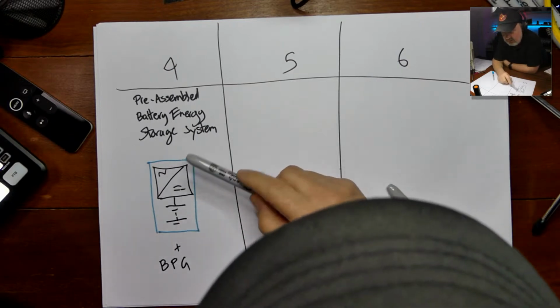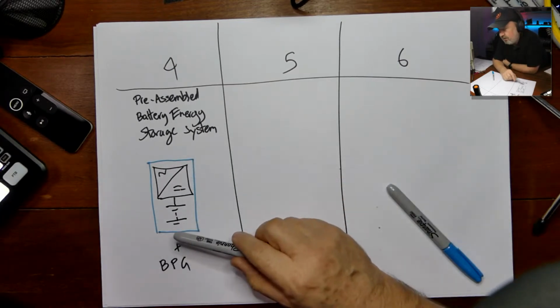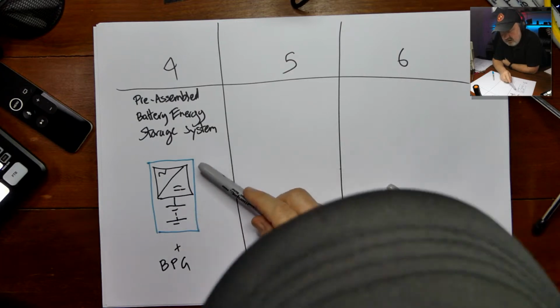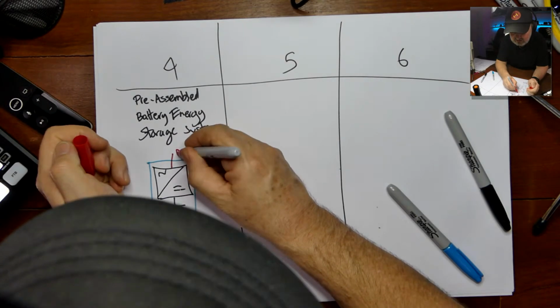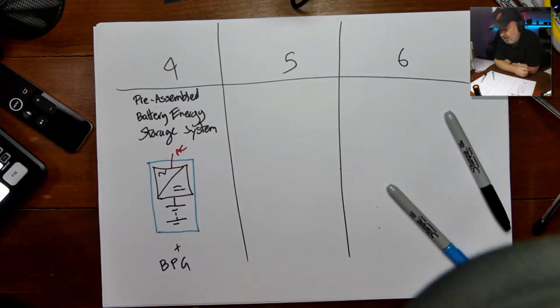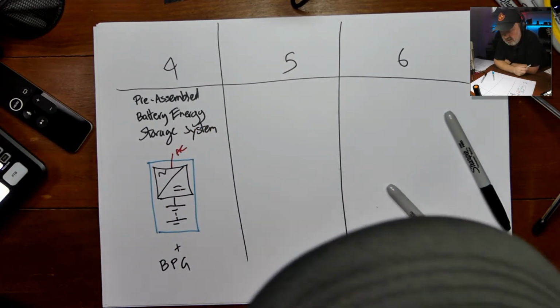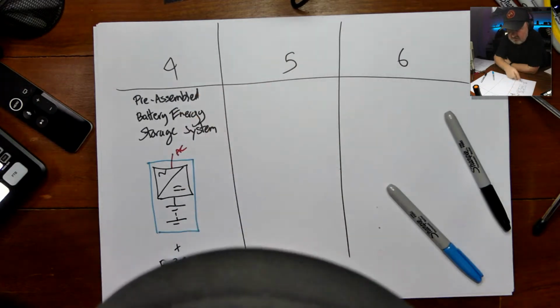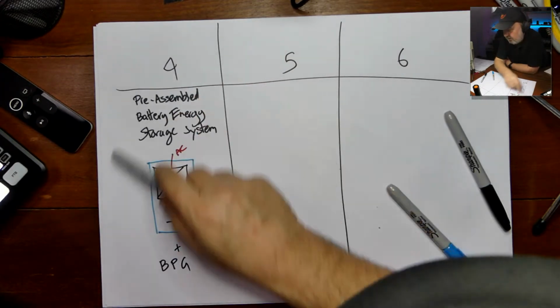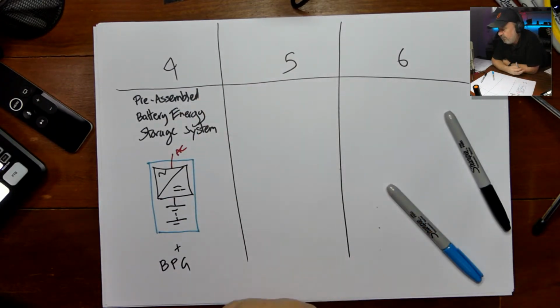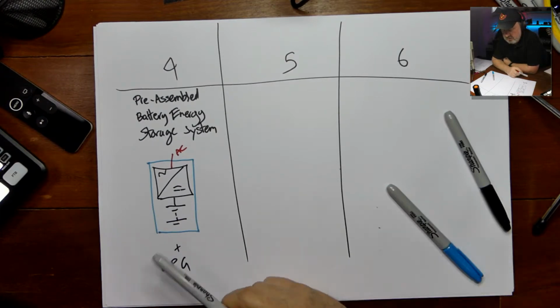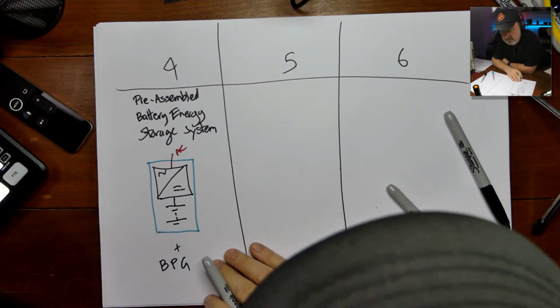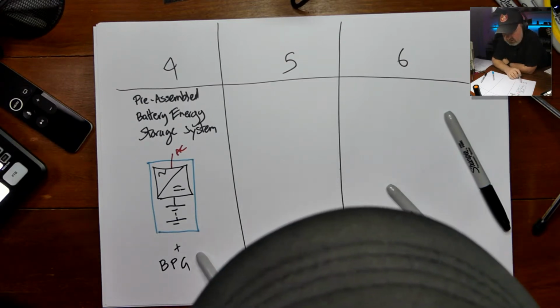So you have to be pre-assembled, with the inverter and the battery as one. Therefore it's an AC output device, so the output of this system is only AC. You don't have any DC terminals to connect to, and it's a Section 4 solution. Products like Sonnen battery, Tesla, and Varta are some examples of an all-in-one BESS, battery energy storage system.